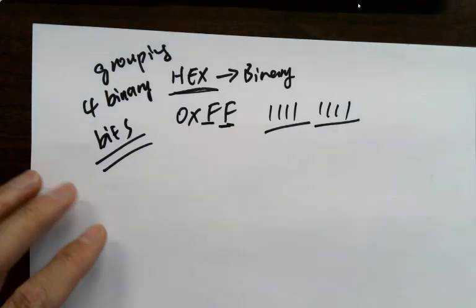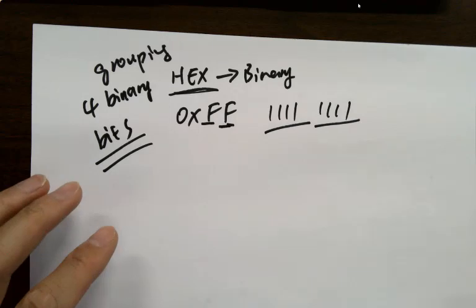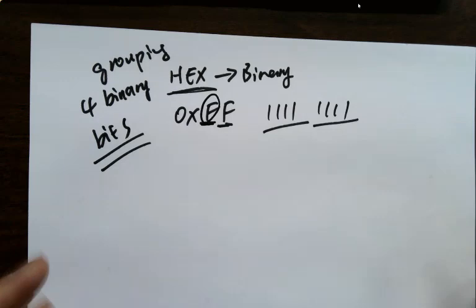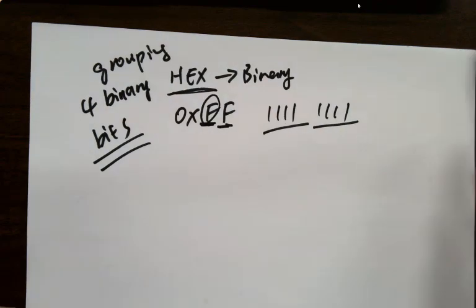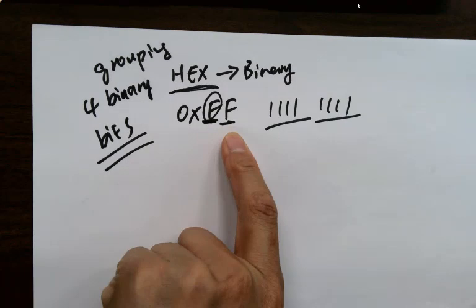Why do we want to use hex? Because it's super handy, especially when you are dealing with digital systems. You just directly assign digits to the pins. You assign FF and you are giving 8 pins at once, turning 8 LEDs on at the same time. It's just one example. You can manipulate the digital output at the pins easily just using hex numbers: just 2 digits here, but actually it's 8 bits.